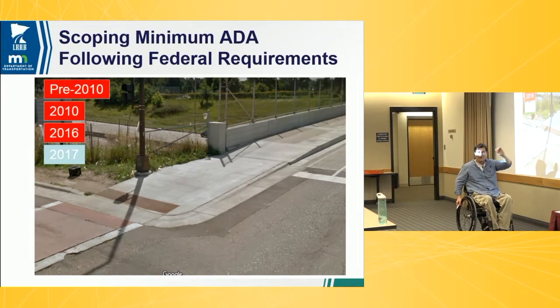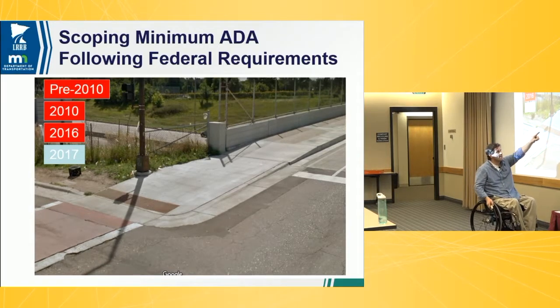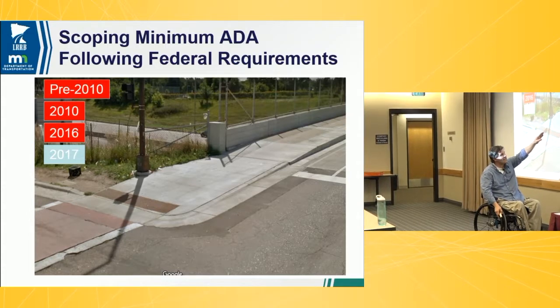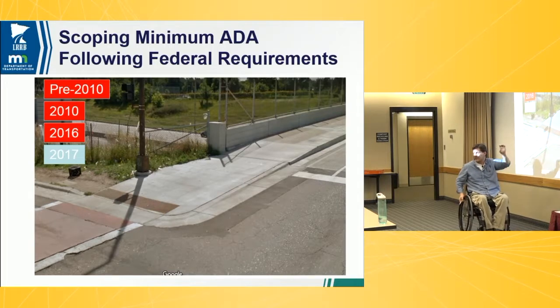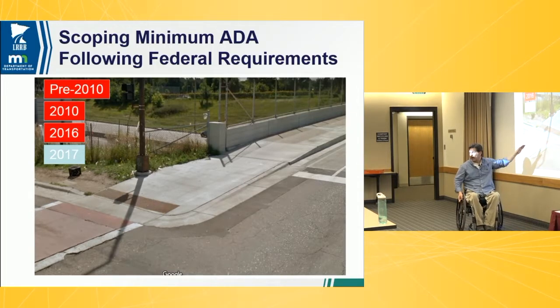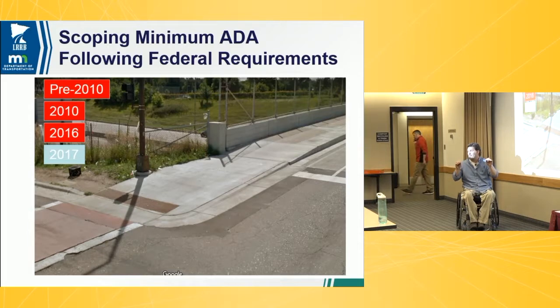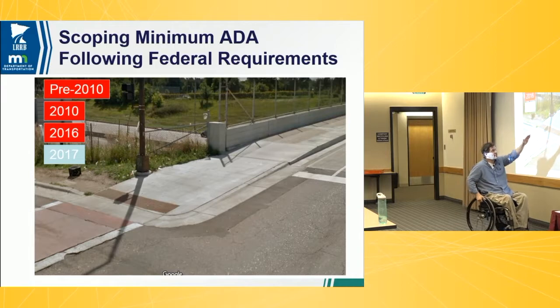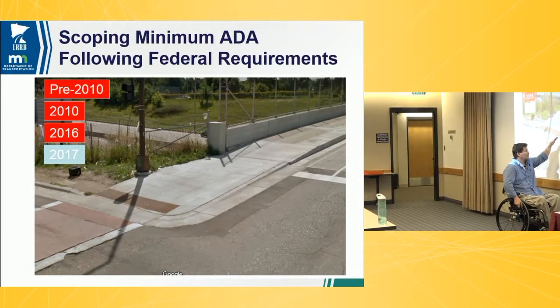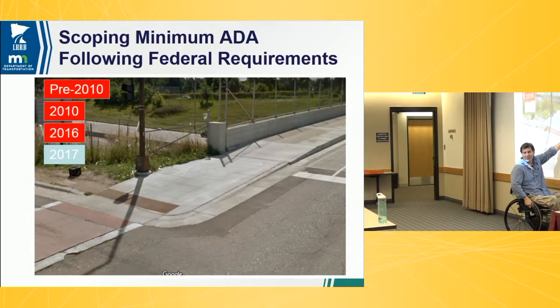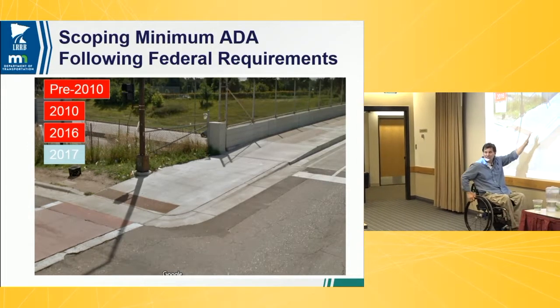But also, now we've got a bridge scope project, so I can actually hammer down that bridge sidewalk. So I'm going from an 8-inch to a 4-inch sidewalk at the bridge, and now I'm tying into that. So I've taken 4 inches off the top, rebuilding the whole curb ramp again. I'll do this piece by piece if I have to, and we'll hopefully get there. But it's still over 8%, and it's hard to see here, but we do have some negative boulevard because we're down lower. And we don't even really have a curb here. It's like a 1 or 2 inch curb, so it's not much of a detectable edge. So we're still struggling with a lot of things.